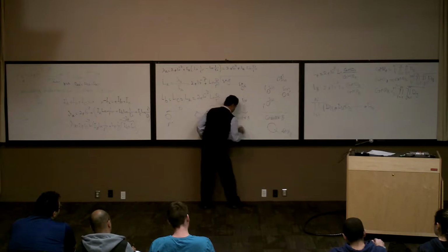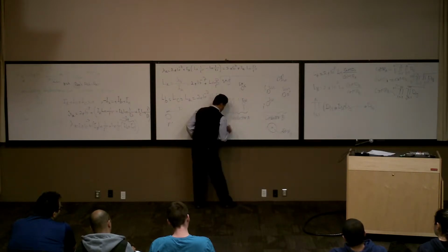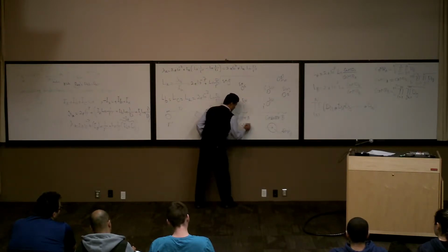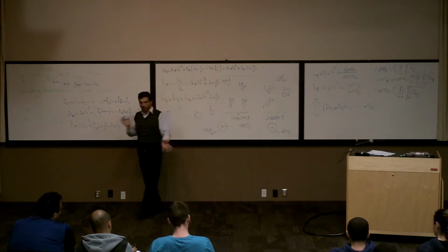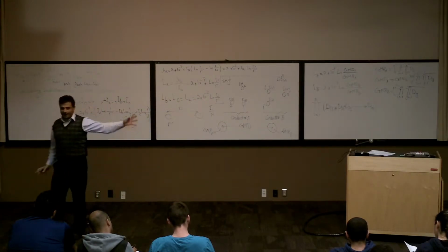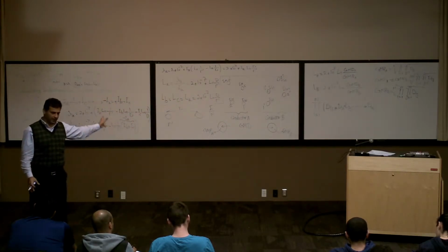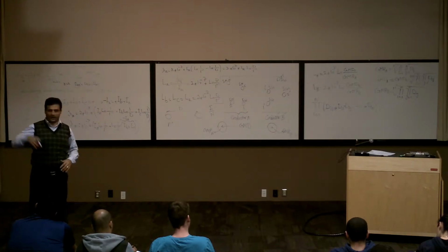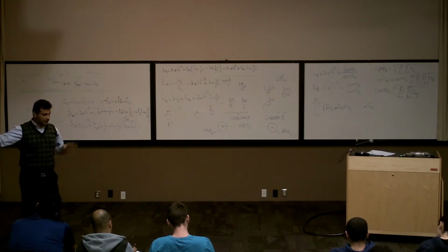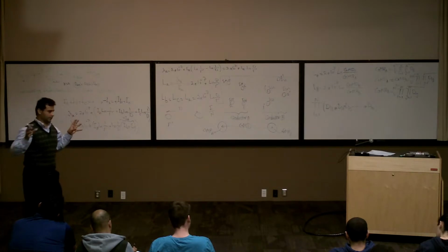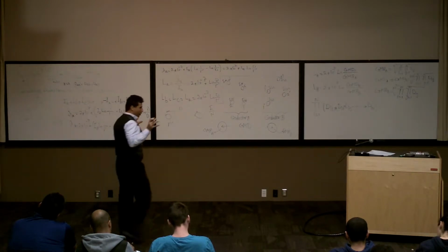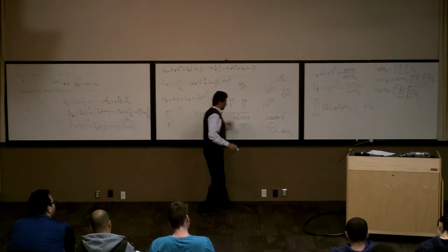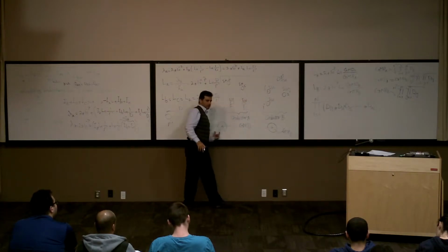And how much is this distance? It's GMD. Basically, you are modeling this system like this. Instead of having, say, 10 conductors for conductor A and, I don't know, 24 for conductor B, you are coming with one equivalent for each. And you're coming with one equivalent distance for these two. We call it GMD, GMR.